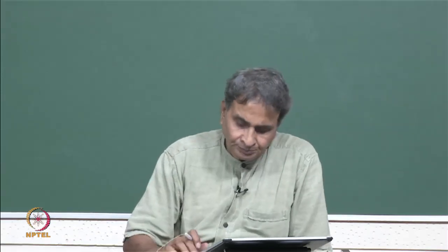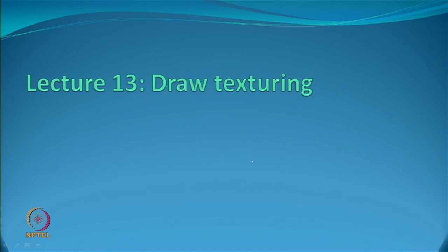So, constraints have changed. We now have another material which will be called undrawn yarn, or which is not a fully drawn yarn. Therefore, because it is not a fully drawn yarn, we have to do drawing, all right, and therefore, this texturing process will be called draw texturing.